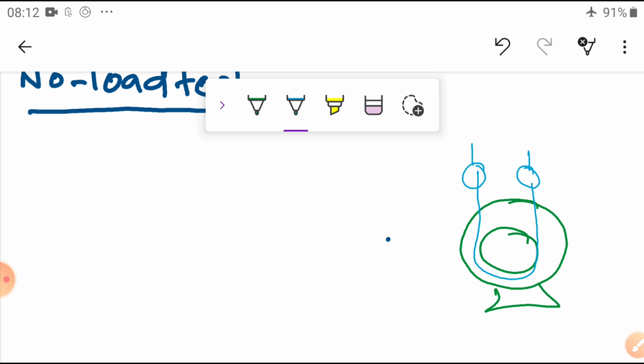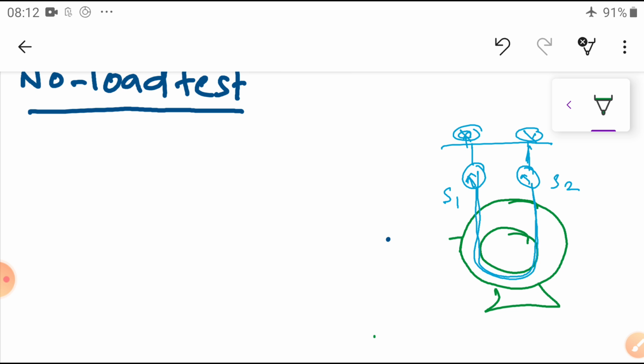From this one I connected to this one with the help of adjustable spring tension. Okay. So, this is the S1 spring, this is the S2. The rotor is connected with the belt. It's the load belt. Through the springs it will show the load on the cage. These are the adjustable springs. Now, I connected this from the terminal box to this one phase, and another phase is connected to this phase.